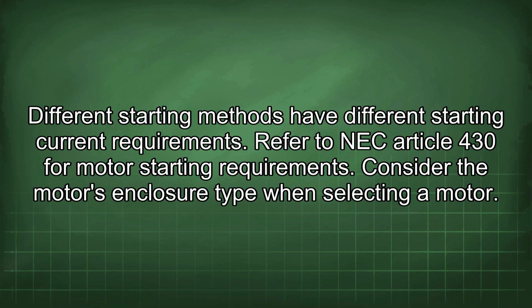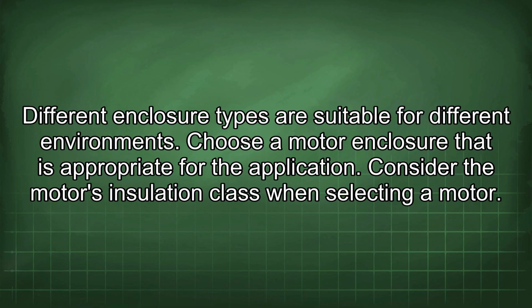Different starting methods have different starting current requirements. Refer to NEC Article 430 for motor starting requirements. Consider the motor's enclosure type when selecting a motor. Different enclosure types are suitable for different environments. Choose a motor enclosure that is appropriate for the application.